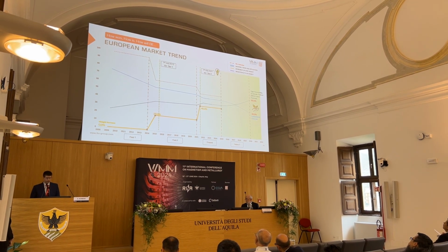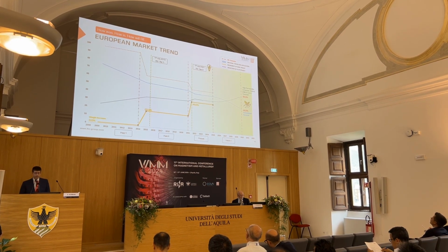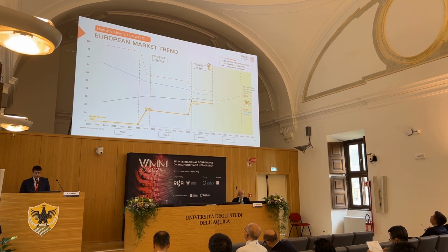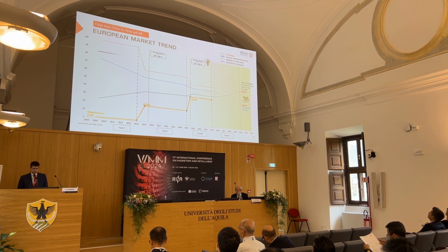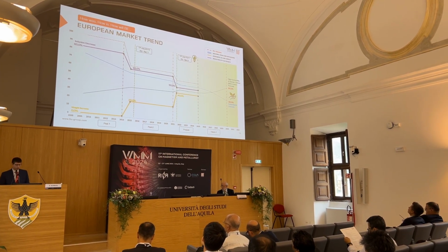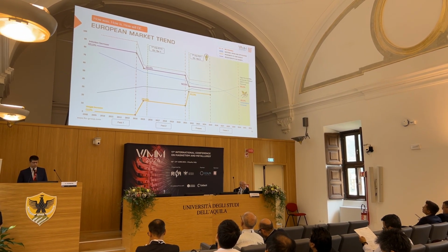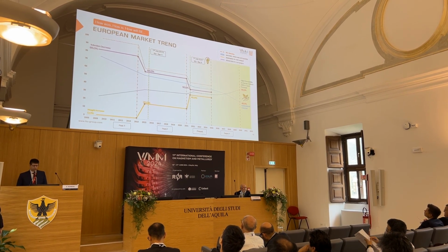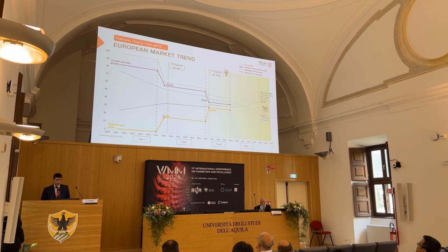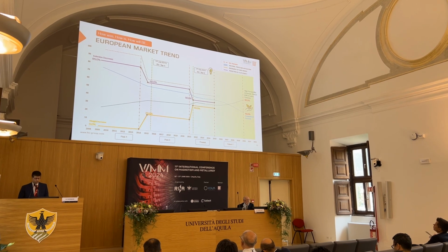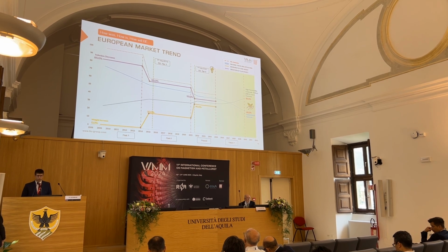So 20% in between 2014 and 2015 with Ecodesign Tier 1, and after 2021 another 20% in support of the Tier 2 regulation. And another step is the reduction of the flux density, which we assume to start from a high value. In the first step it's reduced by 20%, and in the second step again another 15%. In combination, the two, core weight increment and flux density reduction, make this Tier 2 an easier and more efficient transformer core design.